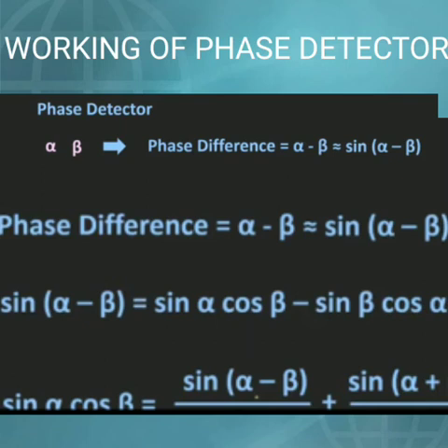The summation signal, that is the higher order signal, will be filtered by the low pass filter, whereas the difference signal will be sent at the output of the low pass filter in order to produce an error signal for the VCO. So by using this error voltage, it is possible to lock the VCO to the input frequency.